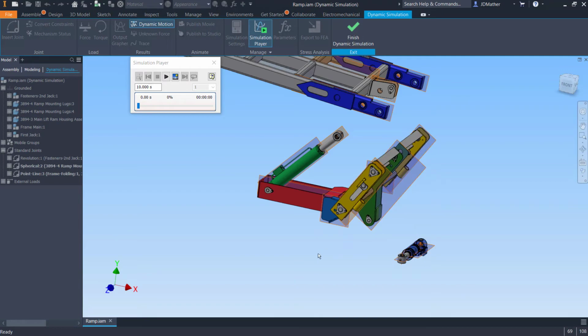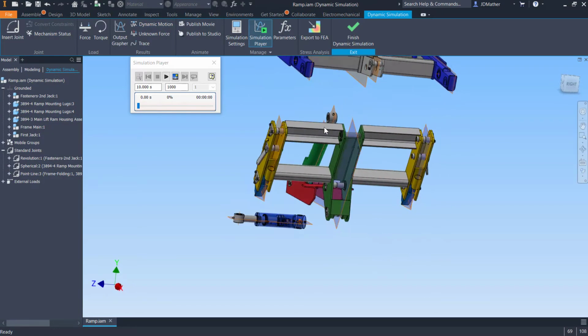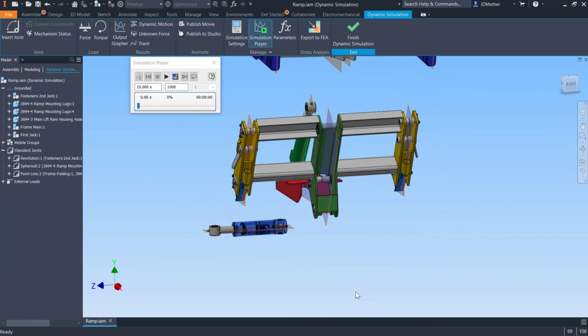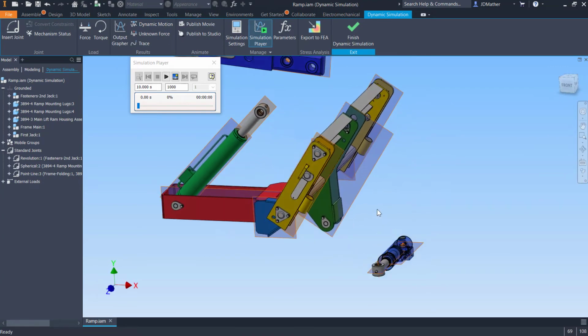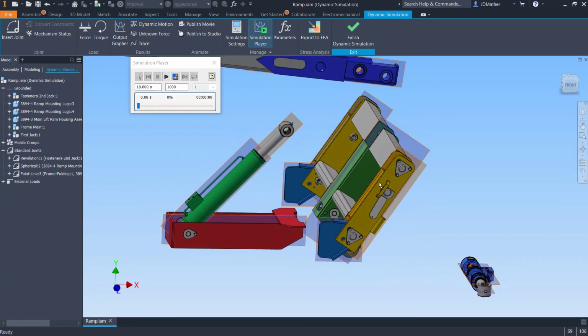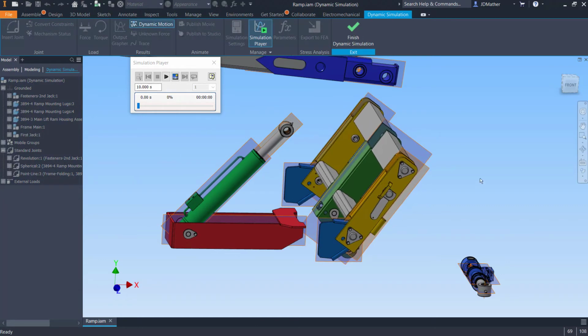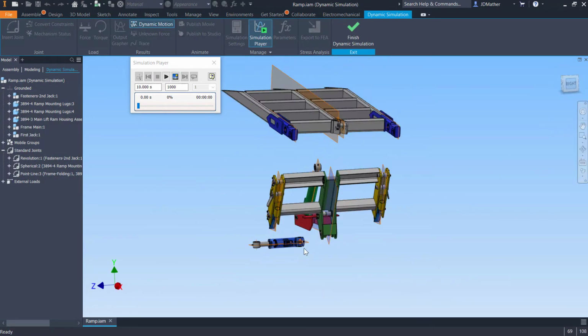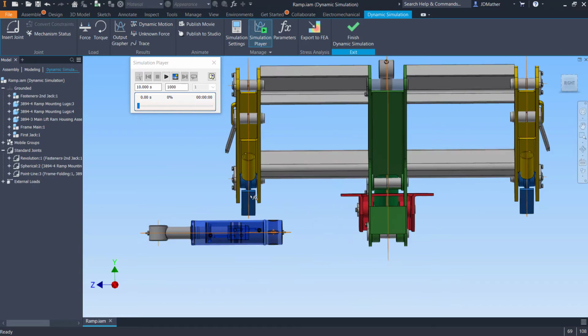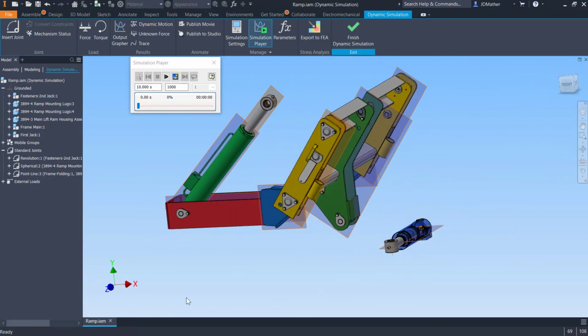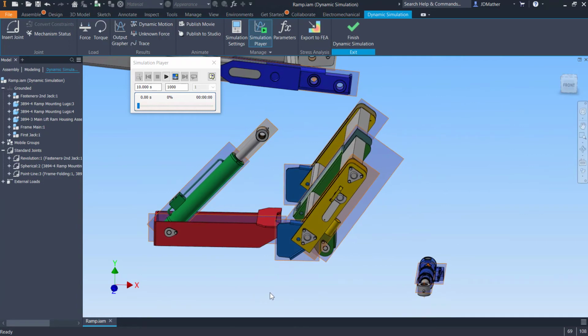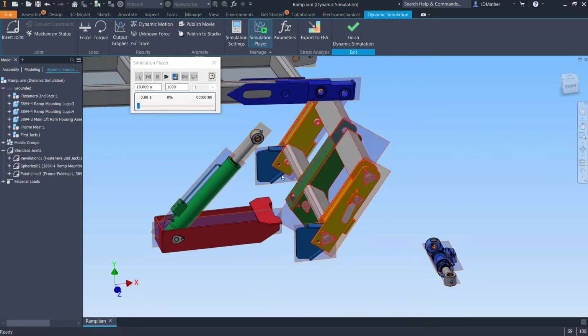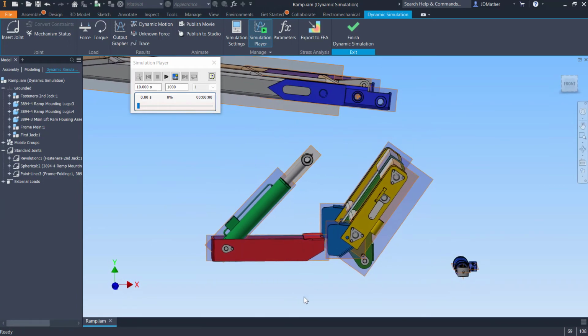It has no translational degrees of freedom. It can't rotate around, in this case, the x-axis. But we haven't over constrained the assembly, because we would have a little bit of clearance between the pins and the fasteners that in the real world could, around the x-axis, rotate ever so slightly, but only a tiny amount. But if we remove that rotation, with an insert constraint on both ends, then it would give us an over constrained condition.